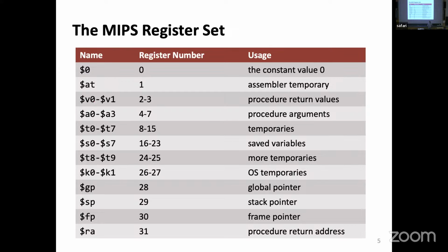Jump and link will store the next address that it would have normally gone to if there were no jump, put it in the RA, while also manipulating the program counter to go to the location of the procedure in question. We will see a couple of examples tomorrow. We will slowly go through a relatively funny program to see how this works, okay? Don't worry, we'll see examples.